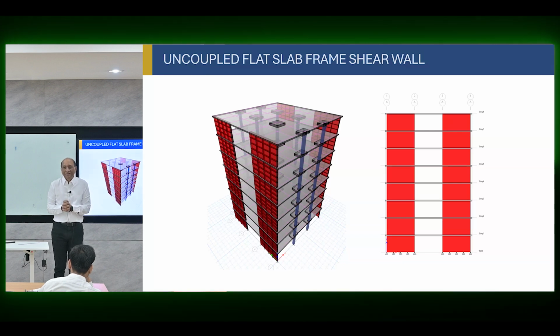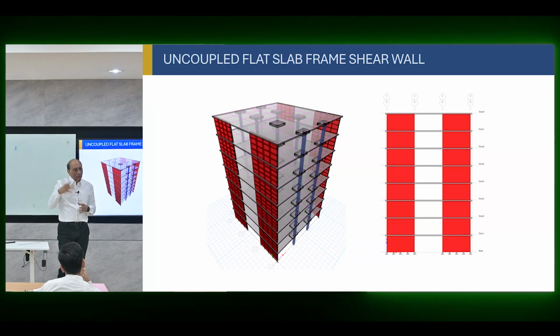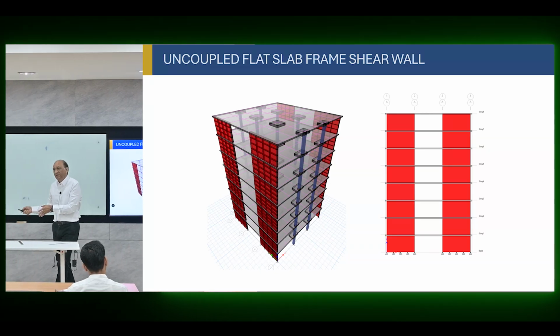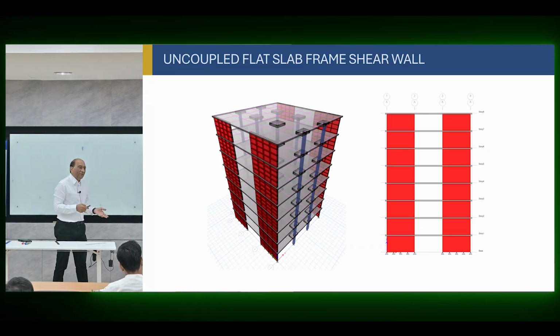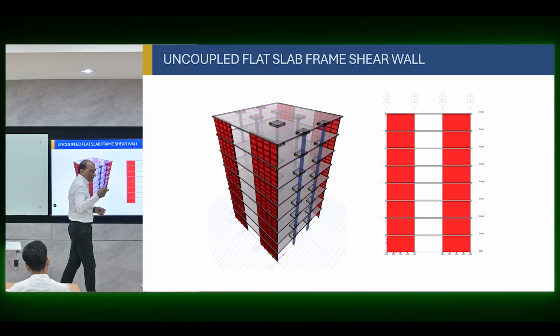And still the bending will be very large, because cantilever walls will still bend a lot. You've seen it. Individual walls will never work. Well, they will work until 20, 30 stories, but beyond that, they will stop being effective. This is the situation: zero coupling to some coupling. So the coupled systems are very good up to a certain height, up to 30, 40 stories.